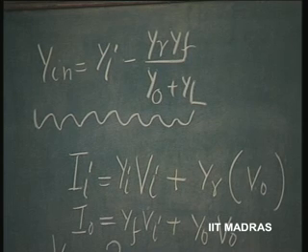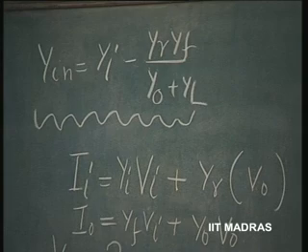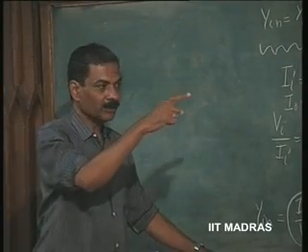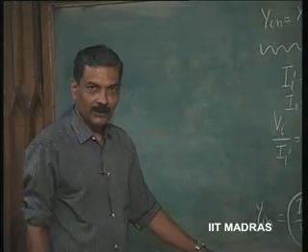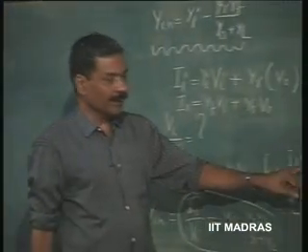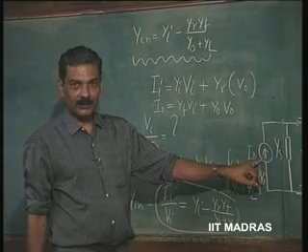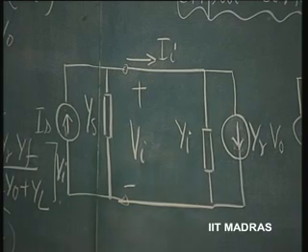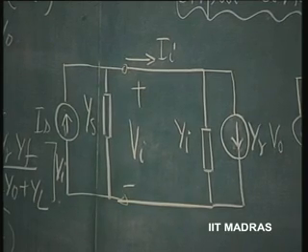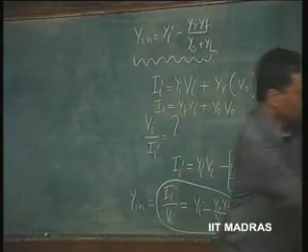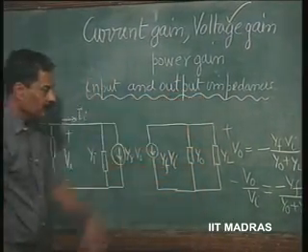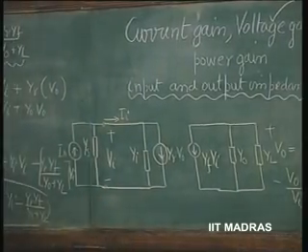In a similar fashion, you can derive the output impedance. What you should do in such a situation is, you should drive the circuit at the output with Is. This is the independent source here, this being removed, Is should be removed. So, you are now looking at the output and seeing what is the output impedance. So, what is output impedance? V naught, you can remove this, divided by I naught. Okay. So, it is exactly like what we have done here.